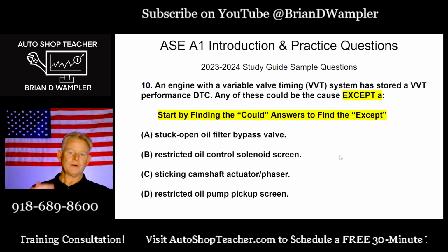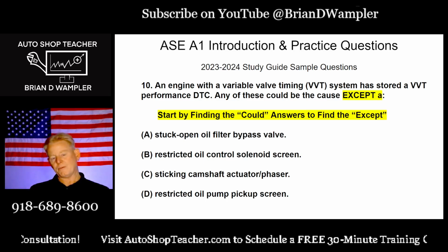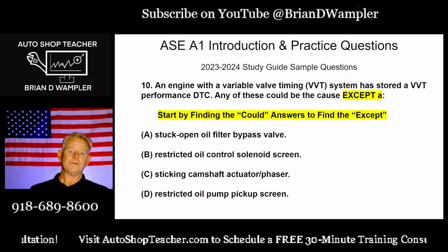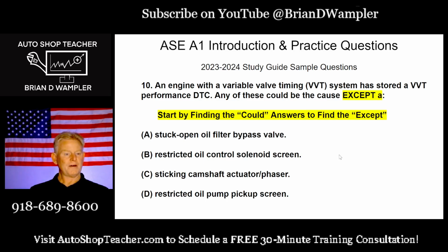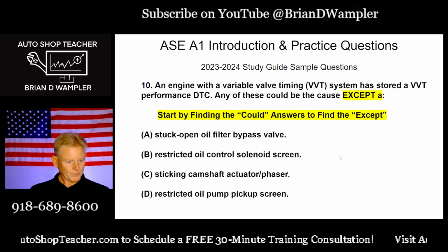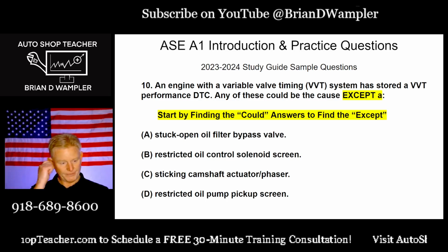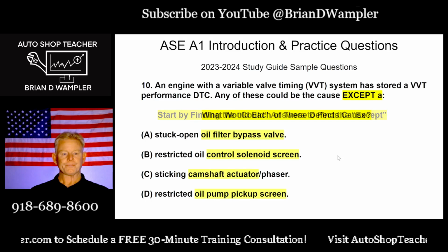Go through and say, okay, I'm going to replace the word accept with could, and I'm going to find the 3 that could, and the one that's left over is my accept. Okay? So could a stuck open bypass, oil filter bypass, could a restricted oil control screen, could a sticking camshaft actuator phaser, or could a restricted oil pump pickup screen.